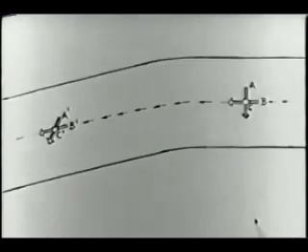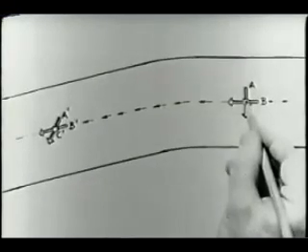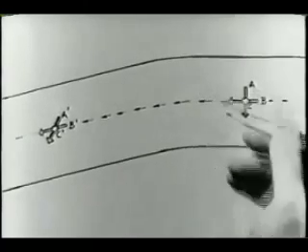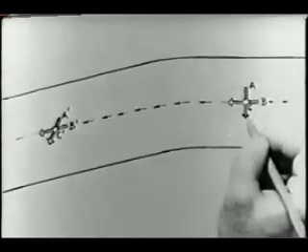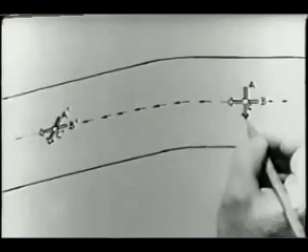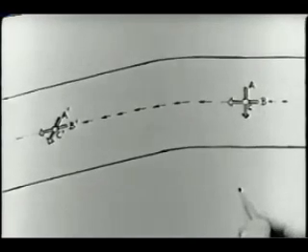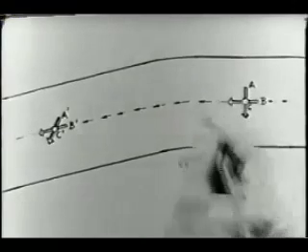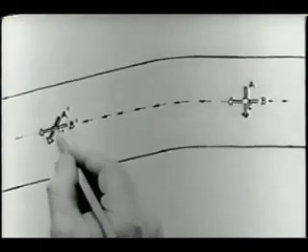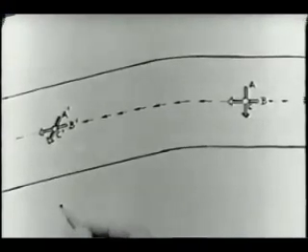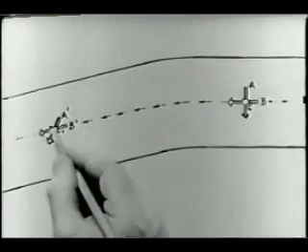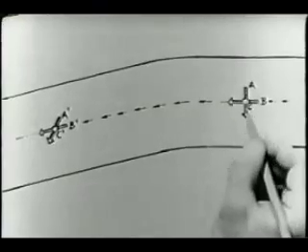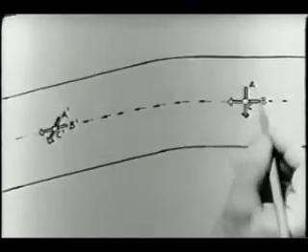Notice, though, that there is no vertical component of vorticity C nor any streamwise component of vorticity B. There is only a transverse component of vorticity A associated with the viscous boundary layer on the floor of the channel. Now line C moves along the center streamline to position C prime, so there is no vertical component of vorticity C prime. The vertical component of vorticity is connected with the turning of the lines A and B.